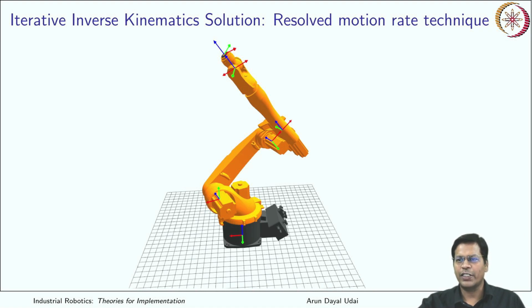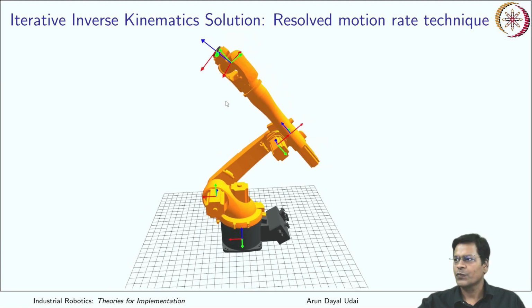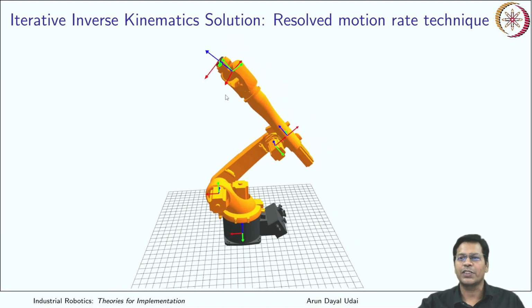If I want to move it along x by a certain distance, 20 I have fed here. So if I start it, you see it has just gone wrong. Okay, some error has popped up and finally it is unable to move. So it cannot move from a singular position. That limit is always there, because this type of technique uses Jacobian inverse and this is unable to move.